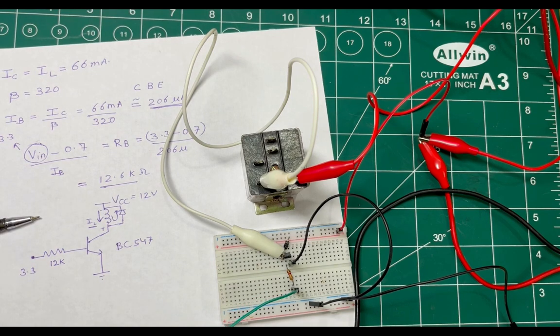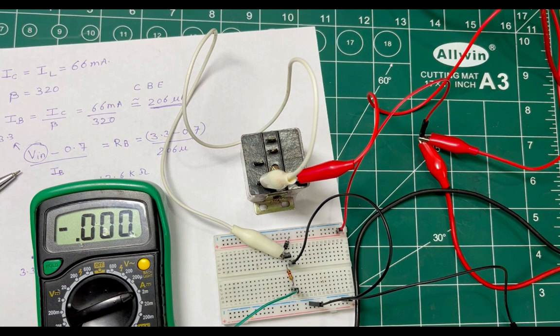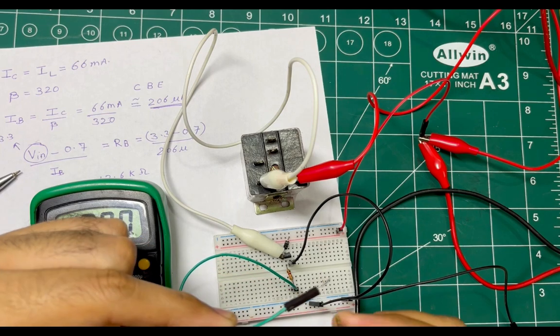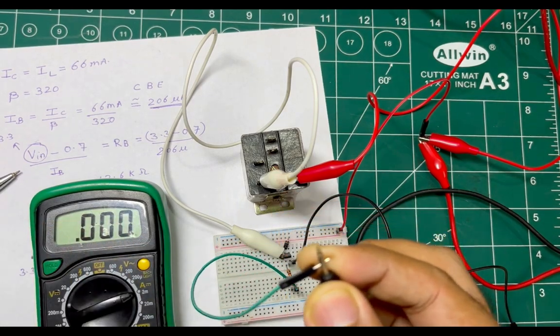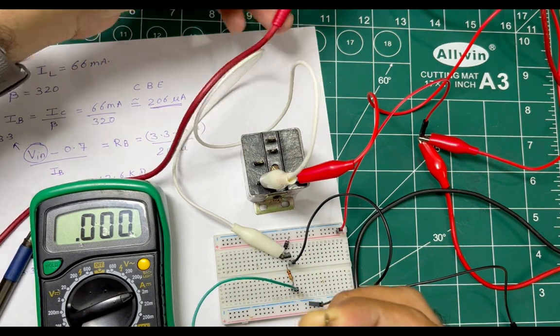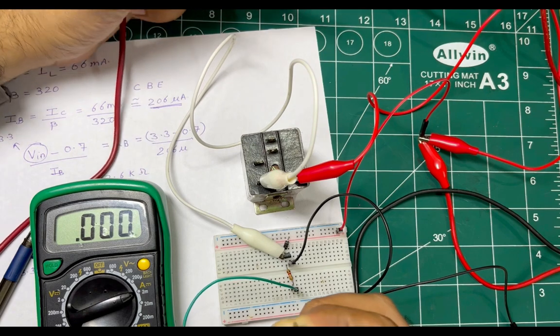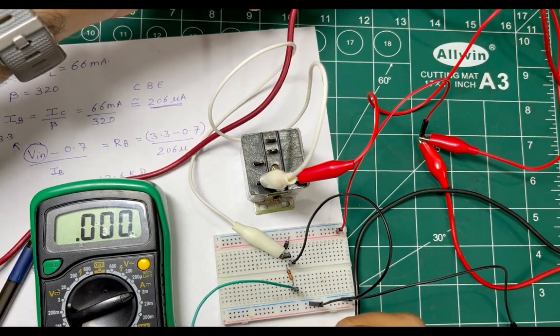What I am also doing here is providing this input to the circuit through the multimeter, because I would like to measure the current that will actually be flowing into the base. So now I am going to connect one probe of my multimeter to the input signal, and the other is going to end up at the 3.3 volt. Now if the circuit works, we should hear the relay clicking. Let's see.